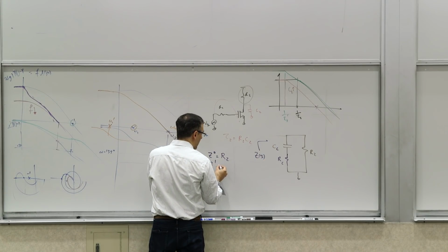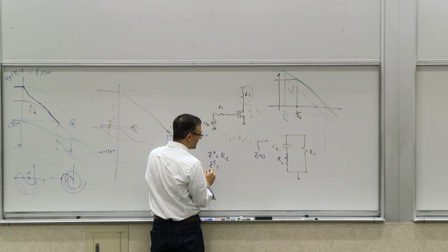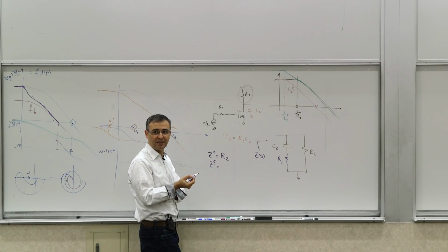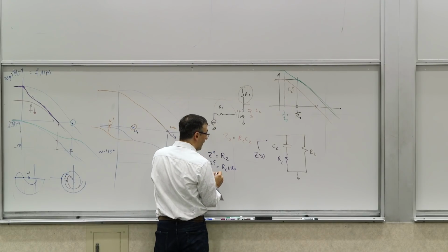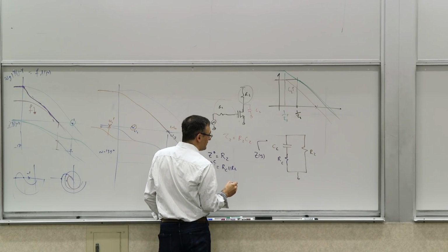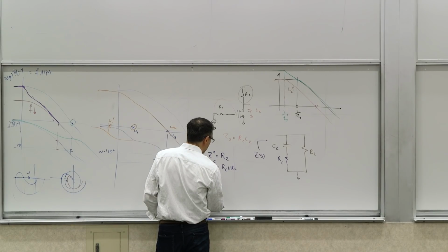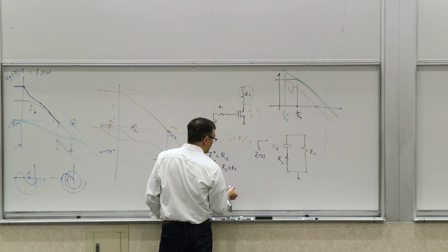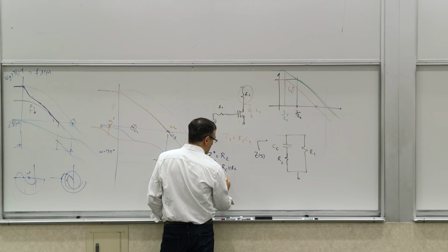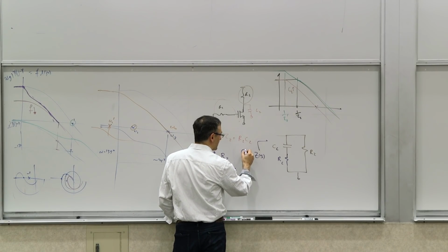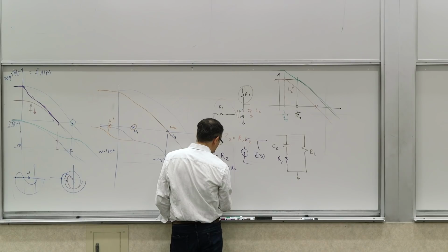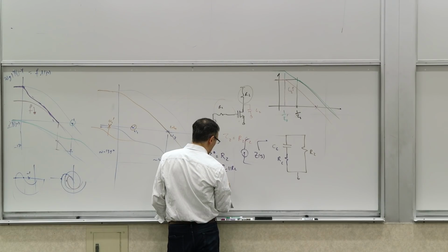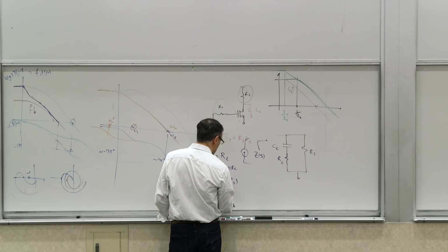What is Z1, or whatever, Z_C, when CC is infinity? Parallel combination, RC parallel R2. And then the other time, you have to calculate the time constant, so you have a tau_C, which is what? We are calculating the impedance, so we are driving it with a current source, so the null source becomes an open circuit. So what do we get? Tau_C, sorry, tau_C is (RC plus R2) times CC.